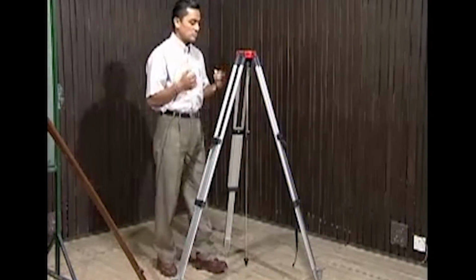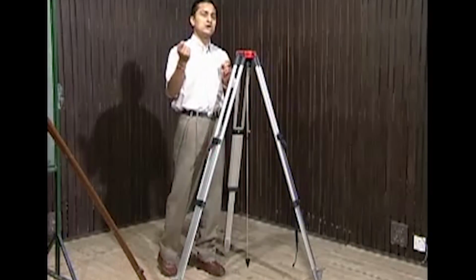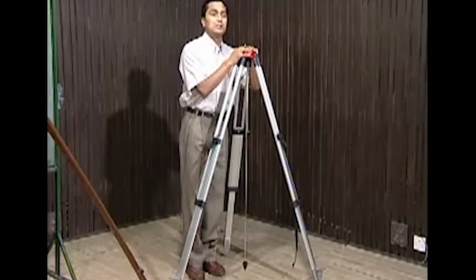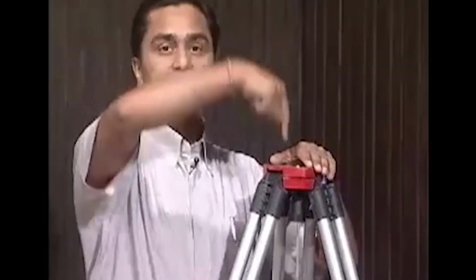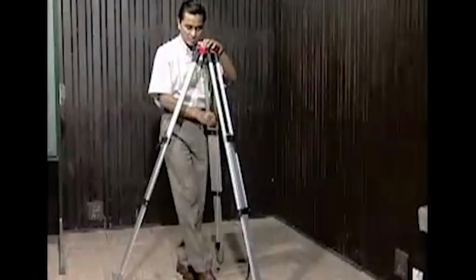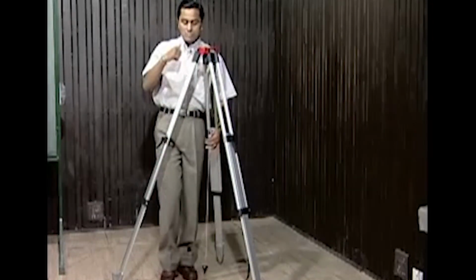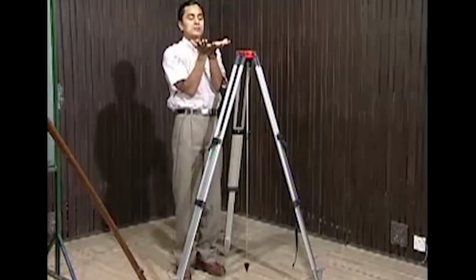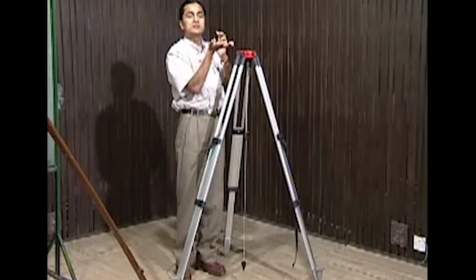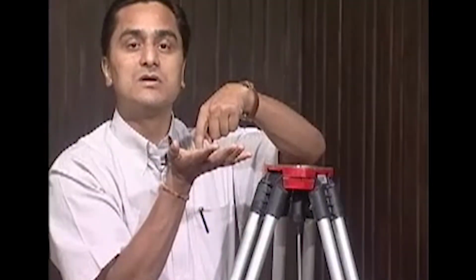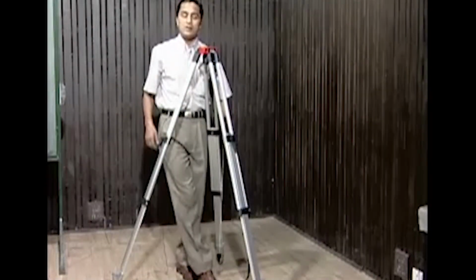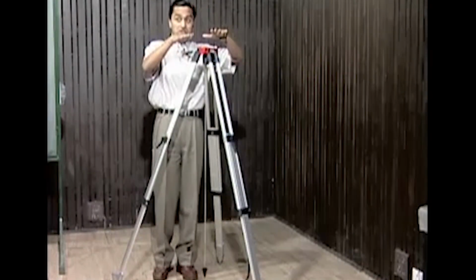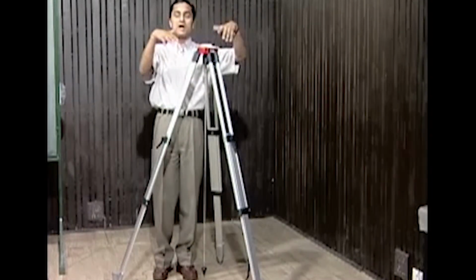Now my job is, because I need to measure the angle A, B and C, I want to put my theodolite in such a way that the vertical axis of the theodolite passes through the point there in the ground. Because the center of the theodolite means where, when I rotate the theodolite horizontally, it is rotating about an axis. That's the point which is the origin about which we are measuring all the angles. So I need to bring that vertical axis over that point. And our theodolite has to be vertical, at the same time the horizontal plate of the theodolite has to be horizontal.